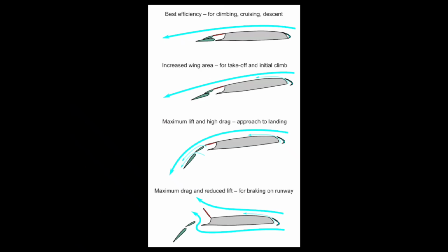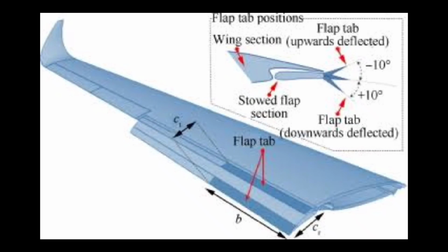When extended further, flaps also generate more drag, which slows the airplane down much faster than just reducing throttle. Although the risk of stalling is always present, generally speaking an airplane has to be flying very slowly to stall when flaps are in use, for example at 10 degrees deflection. Obviously, stall speed and safe airspeed vary from airplane to airplane.